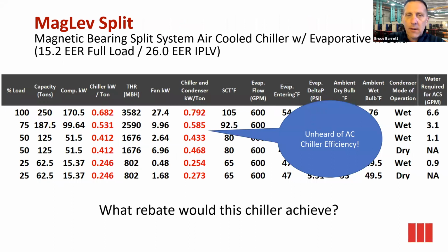So I ran a couple scenarios of chiller performance, and I'm pouring the coals to it. I'm using a lot of water in this application. The efficiency on the left here shows just chiller efficiency, the performance data that we generate. I'm driving that condenser to a design condensing temperature based upon my ambient and my wet bulb. The program does it all for me.